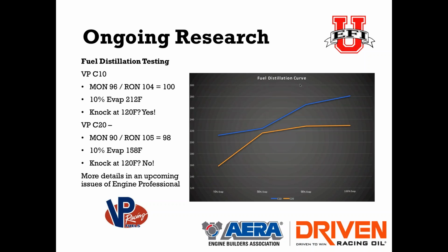And so that really helps us go back to what we saw before in the mixing of the fuel, and how the whole theory of LSPI is really centering around the mixing of the fuel and the oil. If you can evaporate all the fuel, then it can't mix with the oil, then you mitigate the possibility of having an LSPI event and even a knock event.